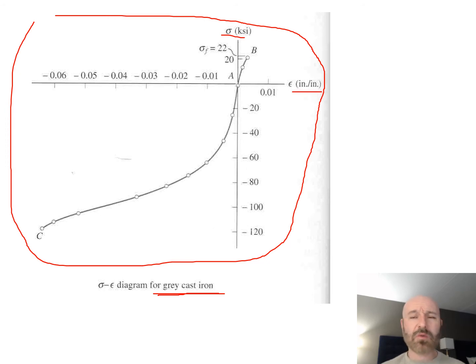You might be saying, do I really want to go brittle or do I want a more ductile material? And come up with that first and decide, okay, yeah, for my application, it makes a lot more sense. I'm seeing a lot more tension right here, and I see the way concrete reacts in tension right there. That's not my best bet right here. Whereas if I had a compression system, maybe these concrete blocks at the bottom here, which held the whole structure up, might be a little better fit for something like that.